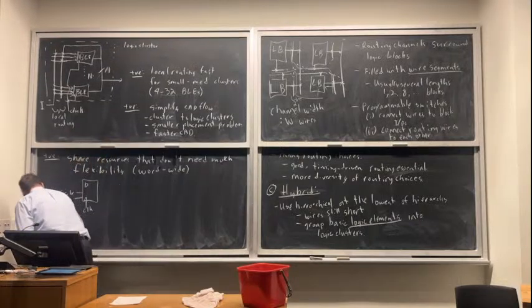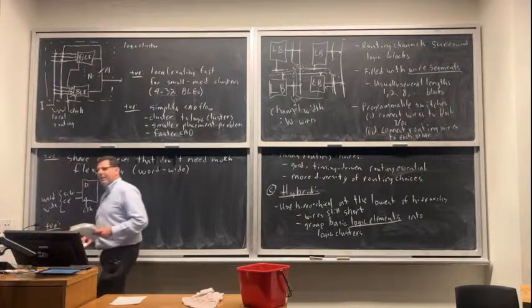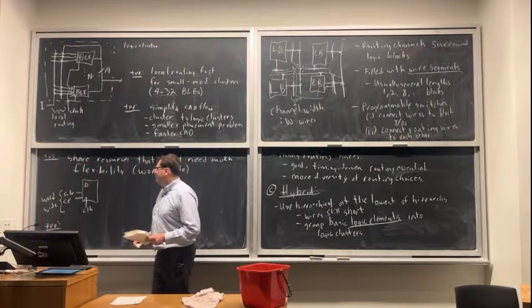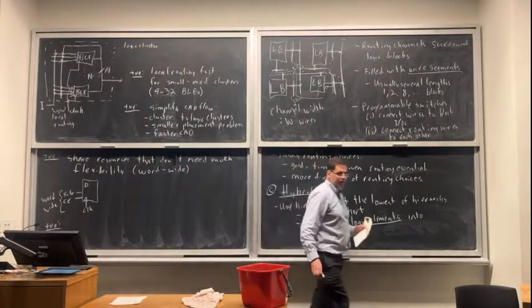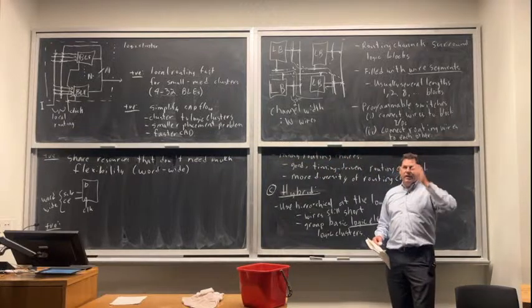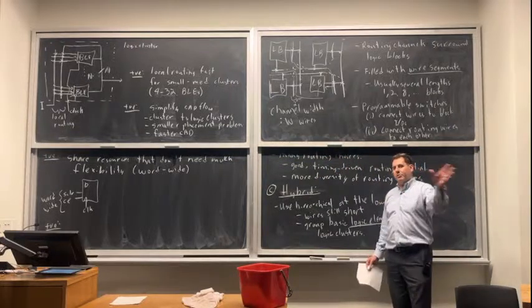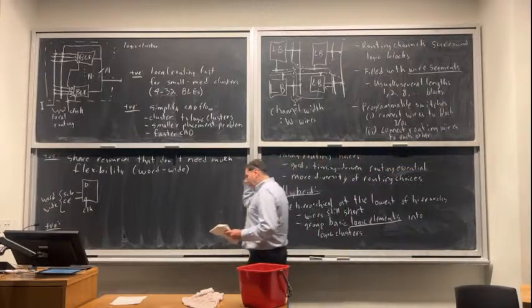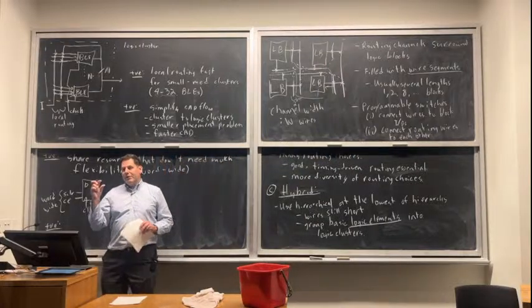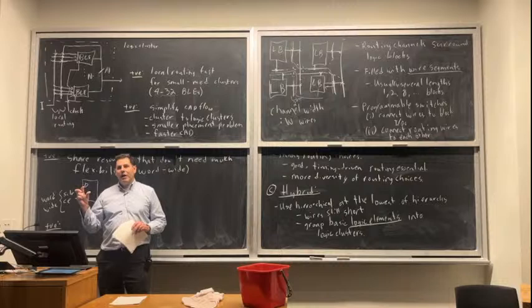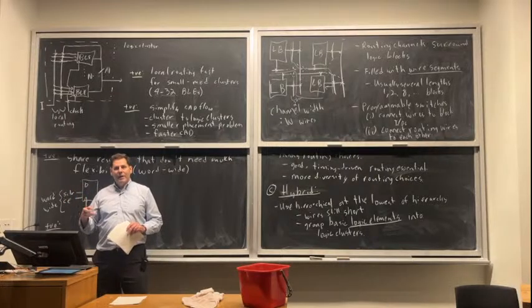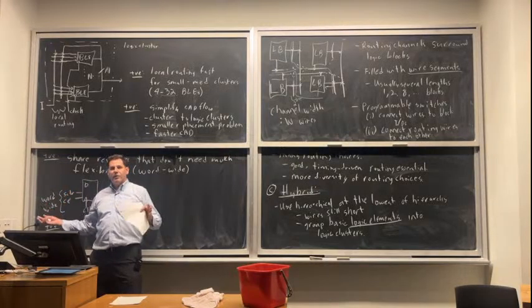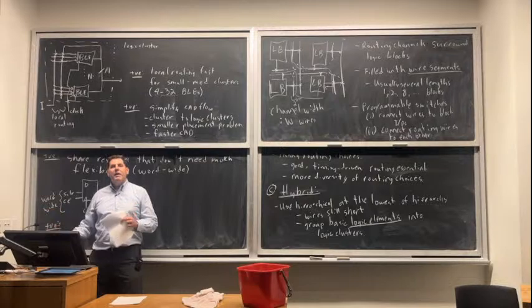Okay, and then the last one is probably very hard to guess. Modern FPGAs don't just have logic blocks. They have logic blocks, they have RAM blocks, obviously they have I/O blocks, they also have DSP blocks that are multiplies and often a bunch of other stuff in with the multiplier. A lookup table is pretty small, right? Say you've got a lookup table that's got 4 inputs, 1 output, and a register after it. That's not that big. If you compare that to a RAM block that might have 8 kilobits of RAM, the RAM's a lot bigger. It also has a lot more inputs and outputs.